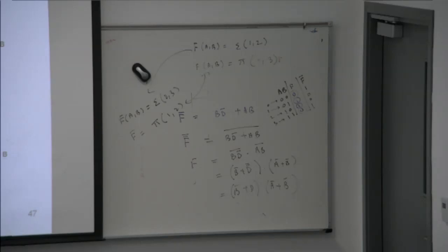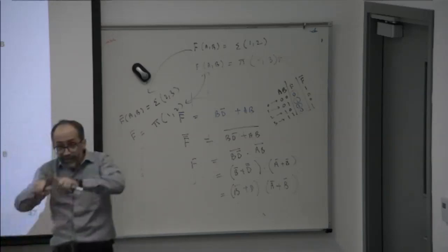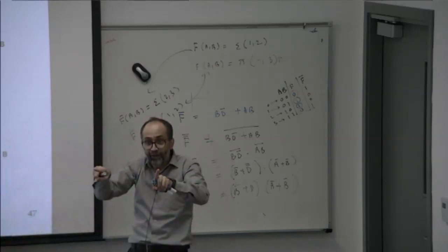If you go through all these examples, what is the advantage of don't care? It helps you in logic minimization. These don't cares can be combined with ones to further simplify your logic expression. In the first expression, we did not consider the don't cares, and it gave me a bigger expression. But in the second case, we combined these don't care conditions with the ones, with the same example.